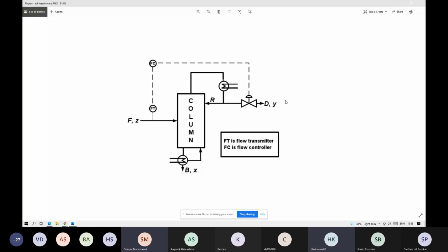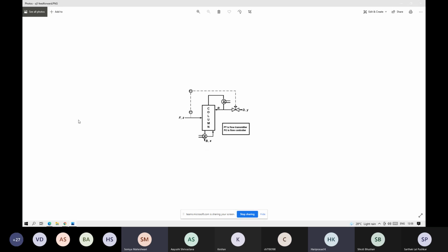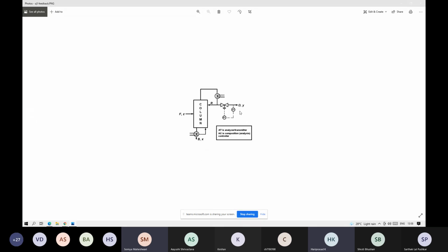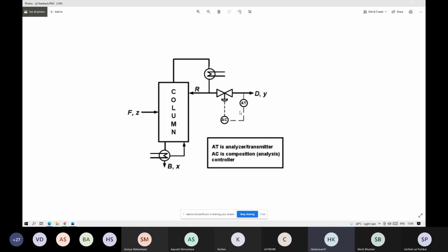Okay, so you are trying to say that, instead of... so go to the next figure. Okay, so your point is, instead of controlling the distillate flow, but you should understand the distillate flow. If you put the lesser distillate flow output, the product would be sent again as reflux, and it would try to improve the purity. That argument you got it right.